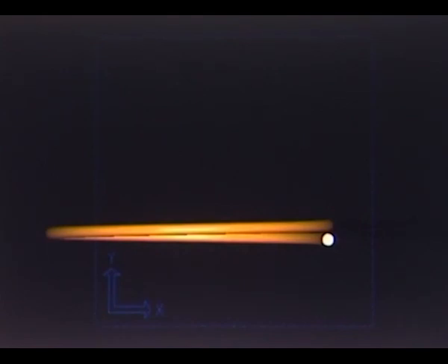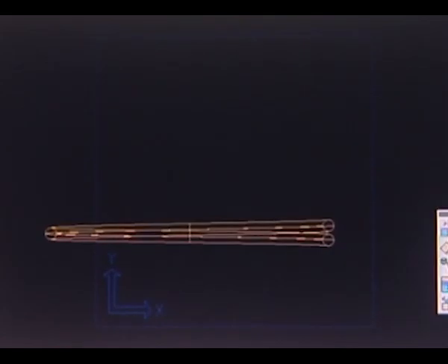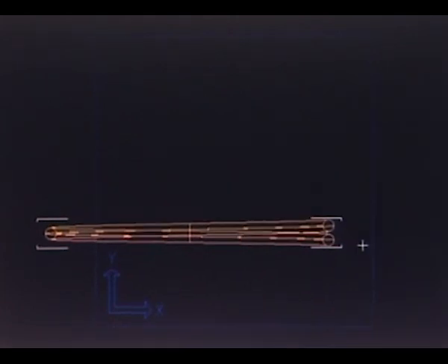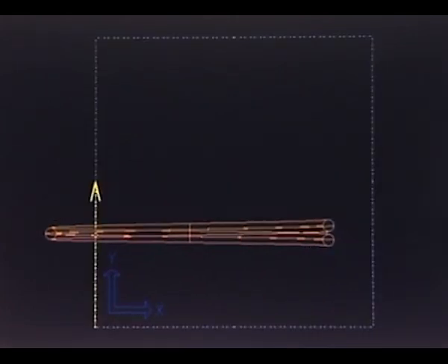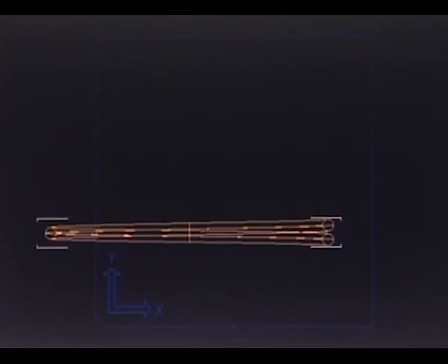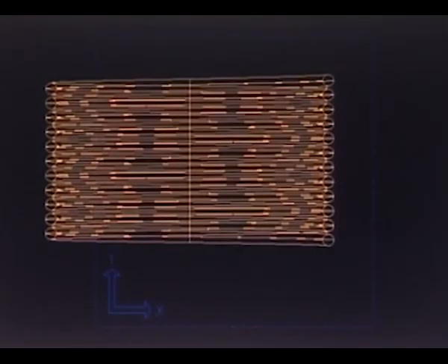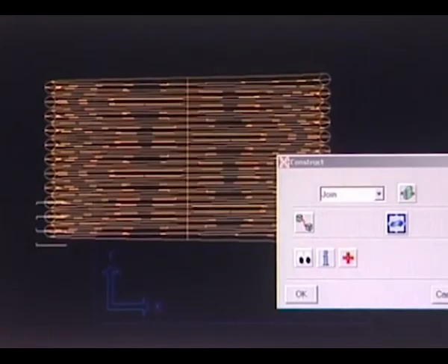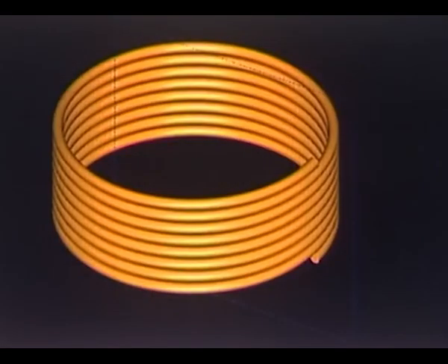We change the display to the wireframe mode, and then we use Boolean options to make copies of this part and join one part with the other. We join two different parts of the spring now. We finally have a spring.